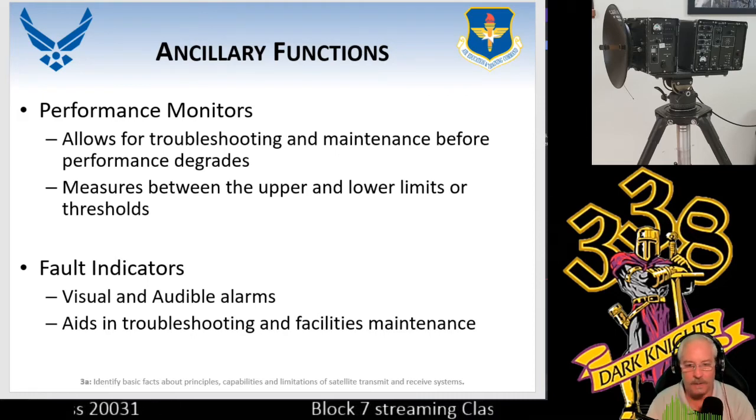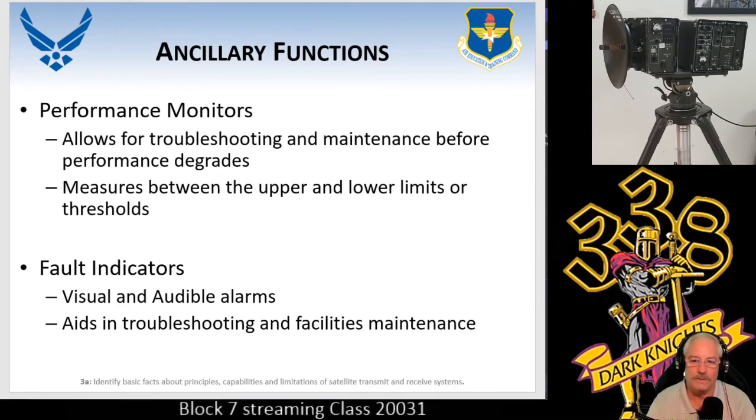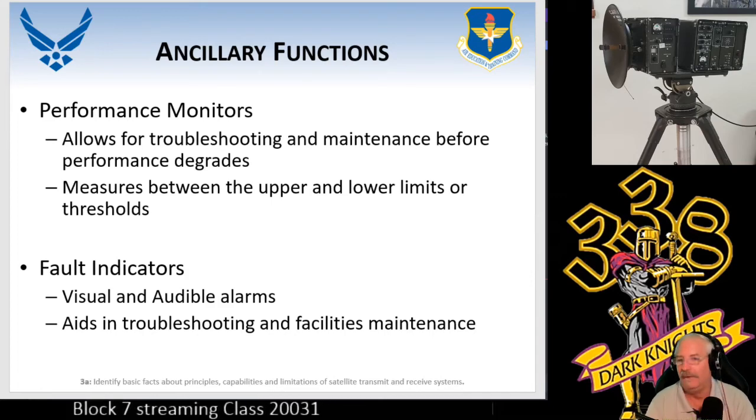For example, I worked in the air traffic control environment, and we had single channel receivers and single channel transmitters. When I got called out at dark 30 in the morning, the first thing I would do is keep the lights off, walk in, look at all the equipment, and find out which one of the lights was off. At that point, it's pretty easy to understand how to fix it.